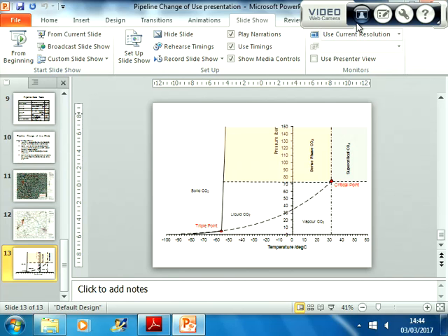But the issue you've got here is, ideally you would be wanting to transport in this phase, but the pipeline's already there, so you're already stuck with the diameter, the wall thickness, etc. So can you actually operate that particular pipeline using CO2 in the dense phase? You need to think about that, and you need to explain your logic.